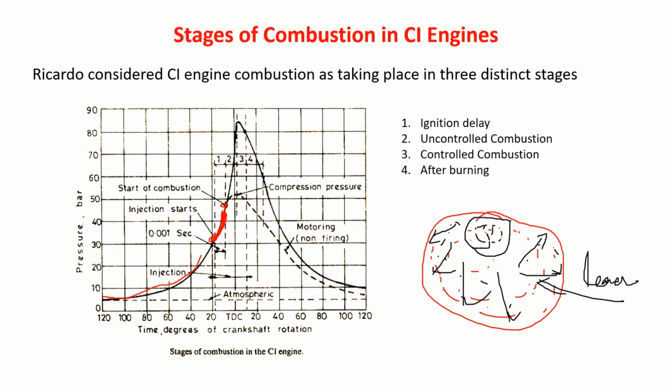Once the injector starts injecting, it continues to inject up till here. So a large amount of fuel gets accumulated in one region. Of course, here also you'll have this, but a large amount accumulated. Somewhere at this point, a flame front will appear. When the flame front appears, it finds a large amount of fuel around it and consumes it very fast. Because of that, there is a sudden pressure increase.